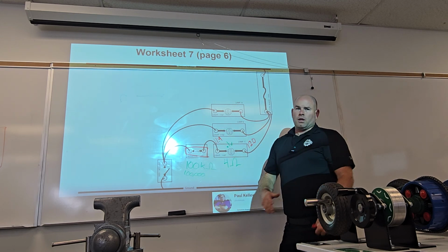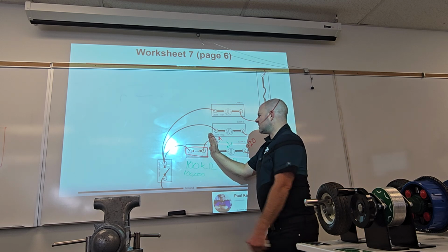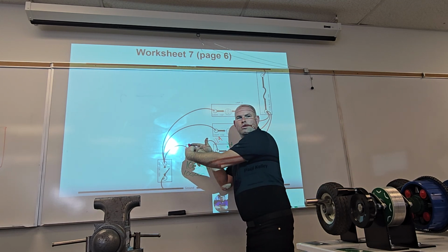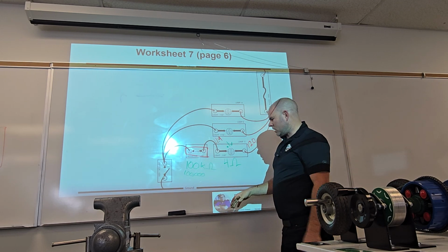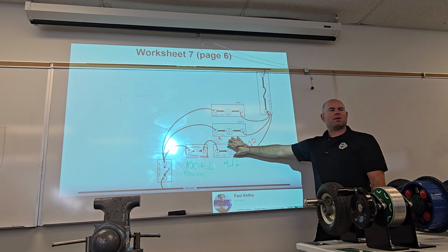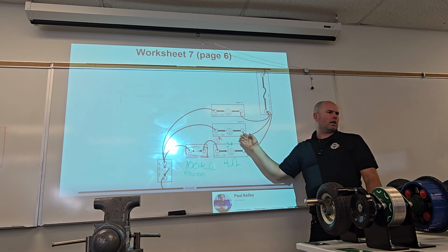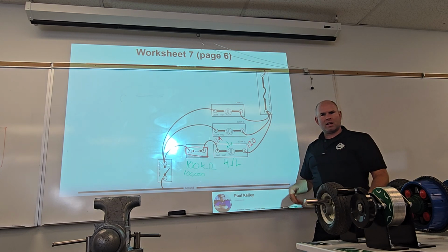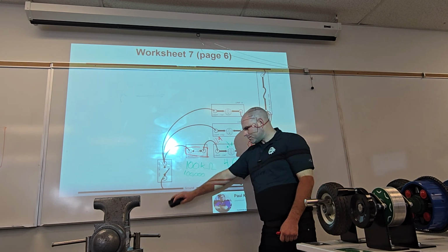Cool, so when we do wire repair, I might cut this out and put in a new connector. And if I put in a new connector, I drop the resistance, I eliminate it, and now this will drop the full 12 volts and this will glow, and then I'll have fixed the light. Make sense? That's how you walk through that.